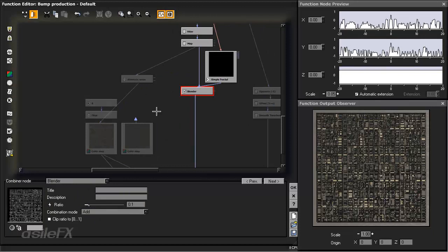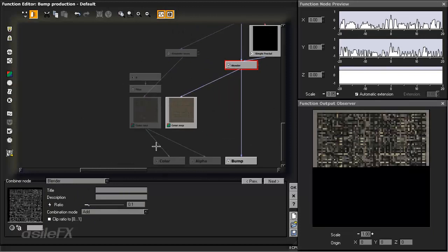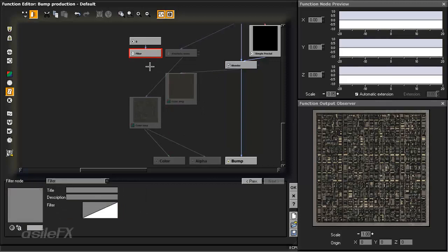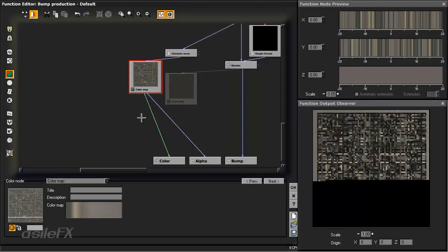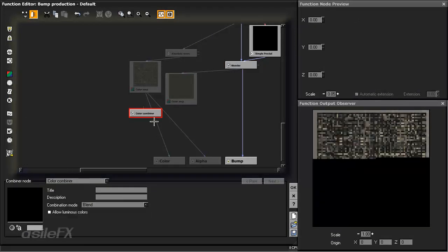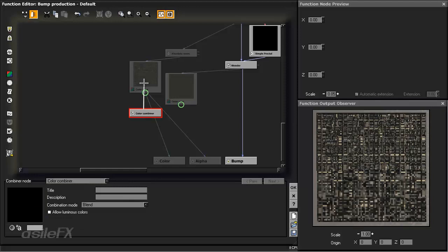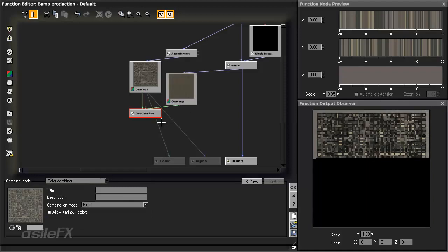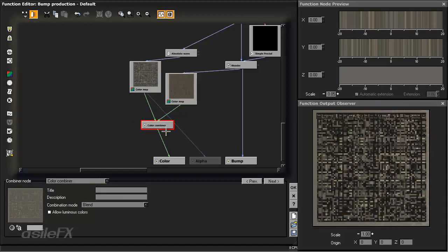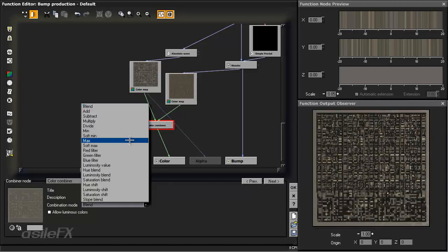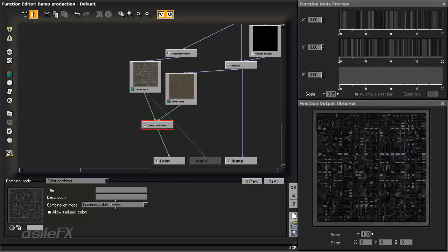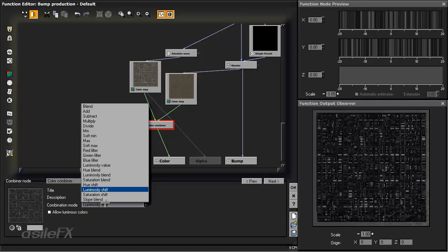And then what we can do is use a color blender or a color combiner. So under the combiner node, selecting color combiner, adding both of those to it, and we can add a lot of different color combinations and then set our mode, which there are a lot of different ways we can modify color and choose a combination mode that has this huge list.